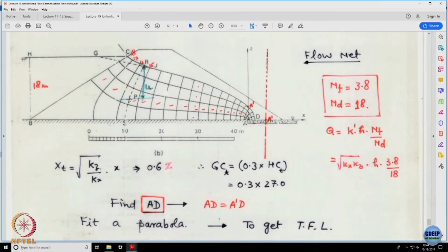At a given point P, if I want to know what is the total pore pressure, the thumb rule is, if the two equipotential lines are known, you interpolate in between, draw the equipotential which is passing through the point P, draw a horizontal layer. If I put a piezometer here, it will go and cut the top surface at this point where the equipotential is cutting the top phreatic line. Point of intersection of the top phreatic line and this equipotential is going to give you the total head at this point. So, once you have got the value of u, you can compute whatever has been asked.